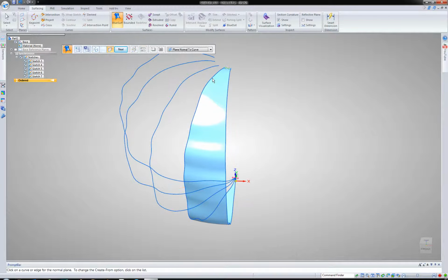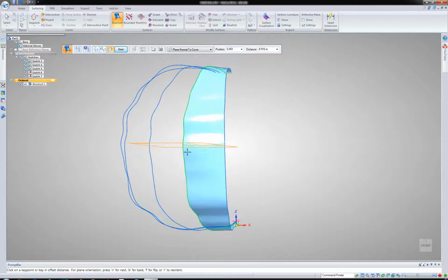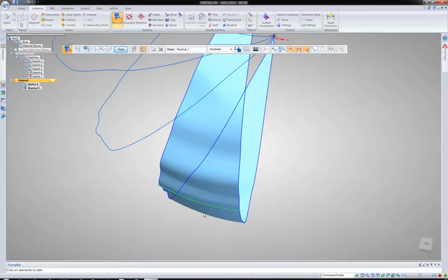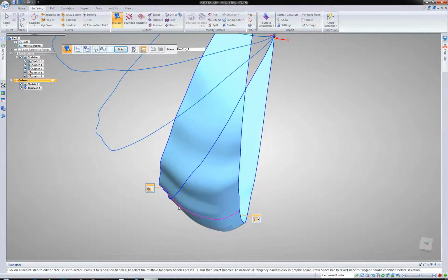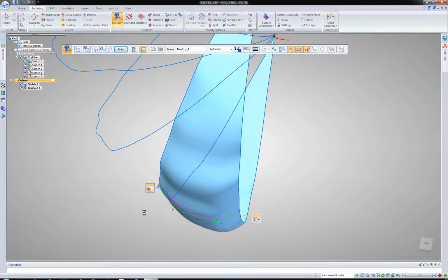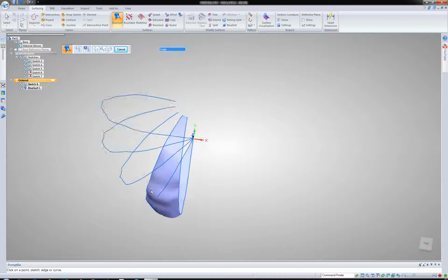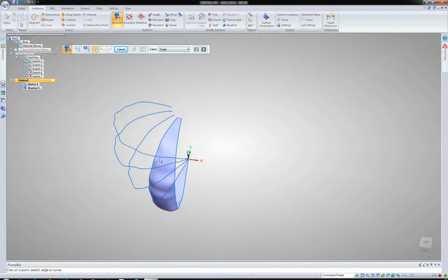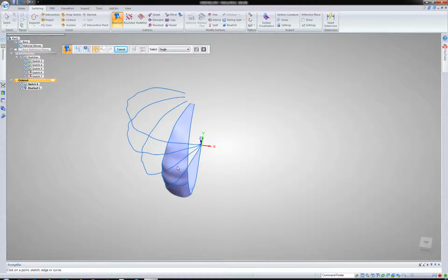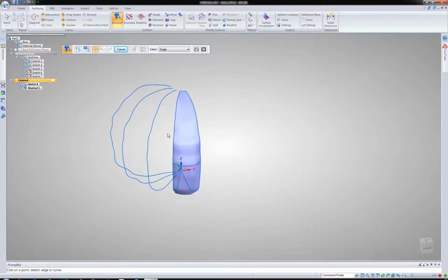What I'm going to do is drag a sketch, and you'll see what's happening here. As I drag along that edge, I can stop. I'm just going to eyeball it towards the middle of here. And now I have another sketch that I can pick and modify. Now you can see I can start dragging this out, giving a little more of a curved body shape to follow along the pattern lines here. There we go. And I can insert as many as I like along this face. Probably 2 or 3 would give you enough curvature all the way around. Even 1 does a pretty good job.